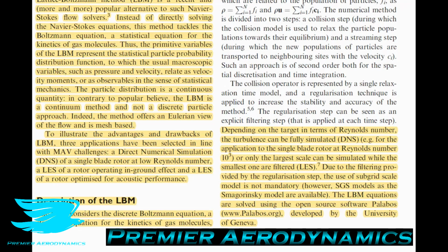To illustrate the advantages and drawbacks of LBM, three applications have been selected in line with the MAV challenges: a direct numerical simulation of a single blade rotor at low Reynolds numbers, an LES of a rotor operating in ground effect, and an LES of a rotor optimized for acoustic performance. I should note that direct numerical simulation is still pretty much beyond us at this point in time. That's why they use LES for more complex flows and faster flows.